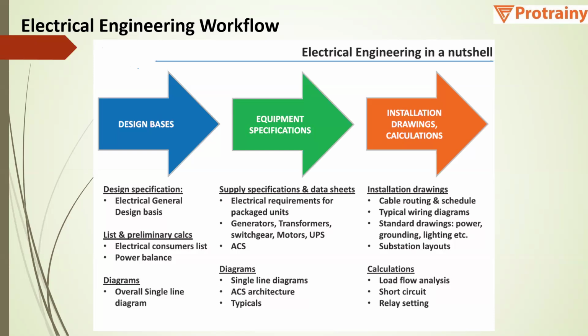Then we have the single line diagram, ACS architecture, typical diagram. Then we have the installation drawings like cable routing and cable schedule, typical wiring diagram, standard drawings like power layout, grounding and earthing layout, lighting layout, and substation layout. And also electrical calculations for load flow analysis, short circuit and relay setting.